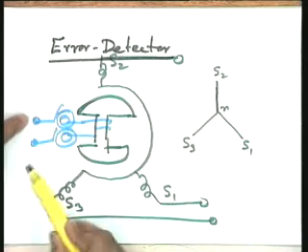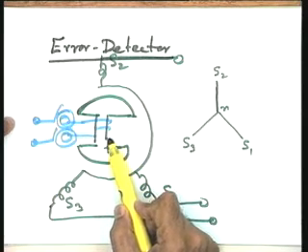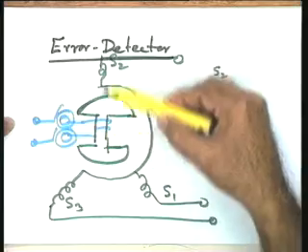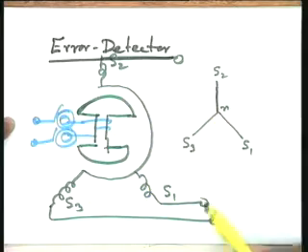Now see this, the linkages of the 2 fluxes. You see in this particular case, when you give this supply, the rotor produces a magnetic flux, and this flux links with the stator windings, and hence EMF is induced at the terminals S1, S2 and S3.